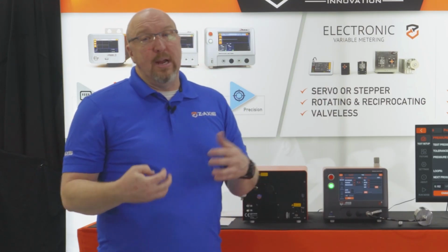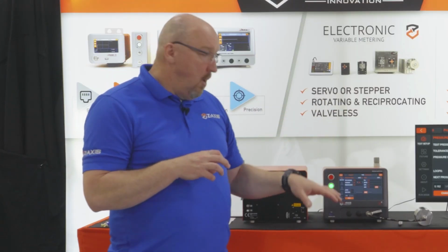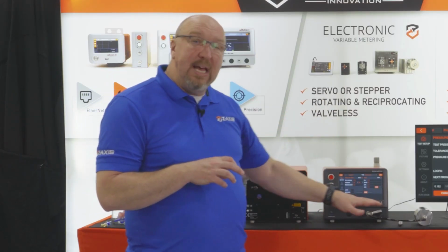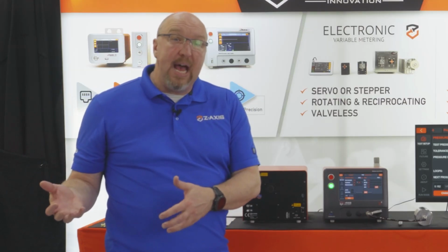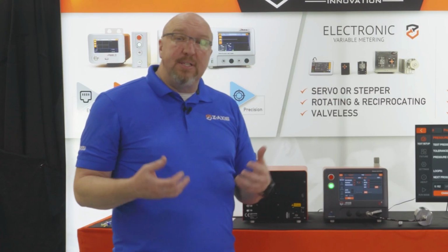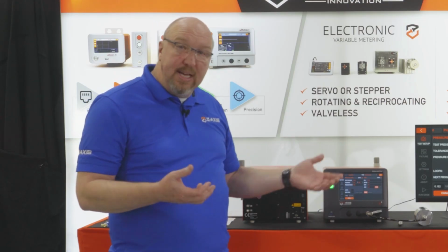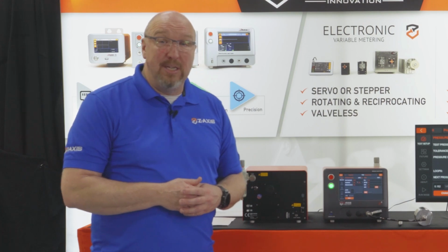So one of the things that we recommend is when we do this process of changing the times, we want to let the part rest. When we go into a production test, we're only going to get 1 chance at this. So we need to better simulate that while we're doing the setup now. So the way to do that is to let the part sit and go back to its virginal state, so to speak.